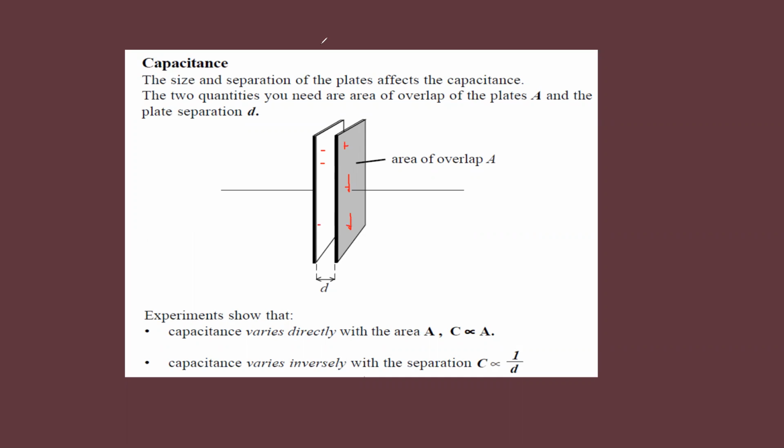But if you put a dielectric or any material between them, it causes a separation of the charge within the material. So then plus minus, minus plus, and minus plus. So you can see a greater number of charges are induced within the capacitor. So it increases the capacitance. A dielectric refers to a material which is having charges. So if you place any dielectric material between the two plates of a parallel plate capacitor, then its capacitance will increase. It can store a greater amount of charge per unit volt.